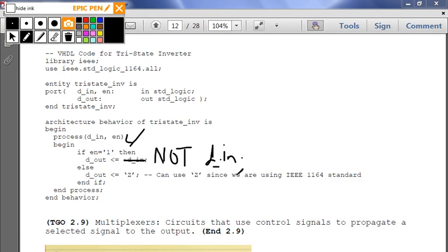I can't remember if you went over this. How do you put multiple buffers in the whole entity instead of having to do it over and over? We're going to be going into that in a little more detail. There's something called vectors, standard logic vectors. As we get into multiplexers, that becomes very useful because you're going to have like 128, 64 inputs where you're comparing 3 or 4 different inputs. You're trying to get a 32-bit output. You can use these vectors to have the 4 inputs and then just map the signals to smaller multiplexers within them.